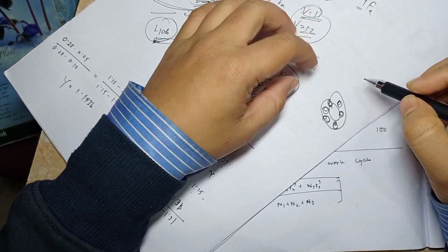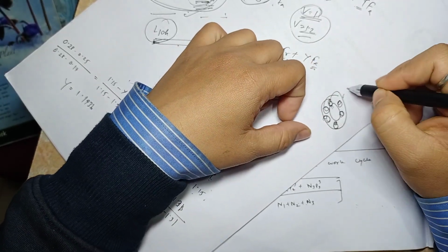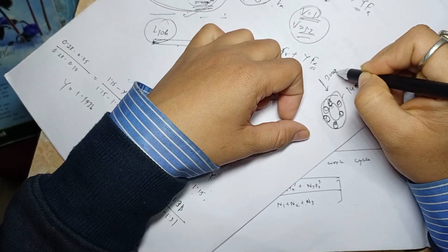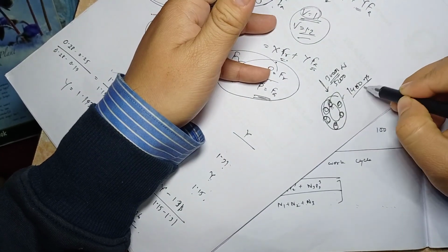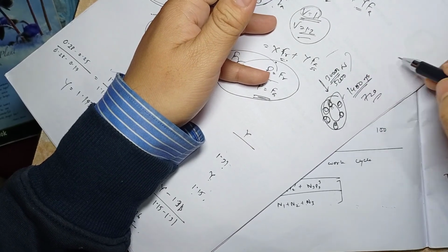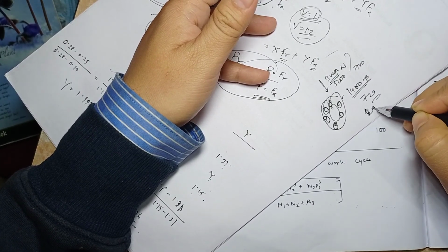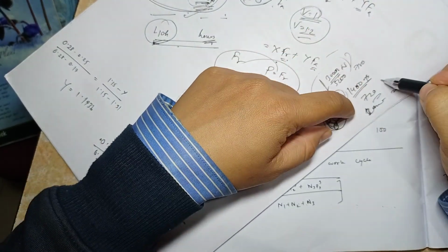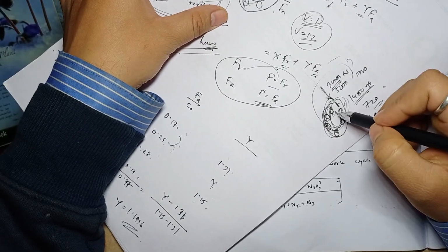For the first minute it is rotating at, let's say, 1400 rpm and is taking a load of 3000 newton. For the next 2 minutes this load will increase, let's say to 5000, and the speed will decrease to 720. For the last 2 minutes it may increase to 7000, and the speed may be, let's say, 2000 rpm. So it is fluctuating. In this case the load is fluctuating and also the speed is fluctuating. So the bearing is now subjected to fluctuating load.